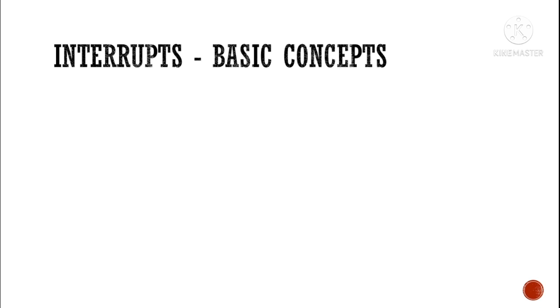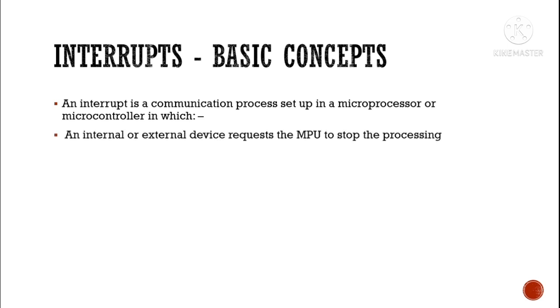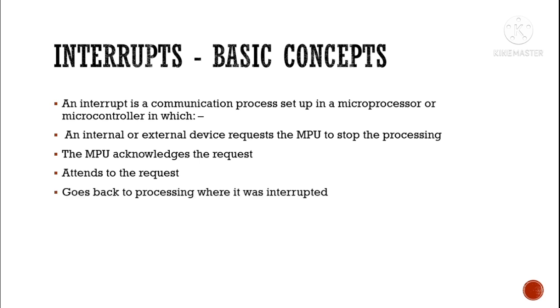Then discuss the interrupts basic concepts. An interrupt is a communication process set up in a microprocessor or a microcontroller in which an internal or external device requests the MPU to stop the processing. The MPU acknowledges the request, attends to the request, and goes back to the processing where it was interrupted. Polling.